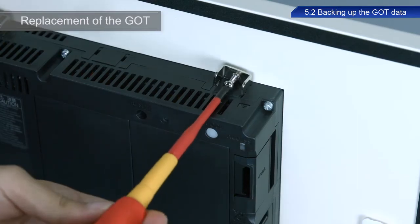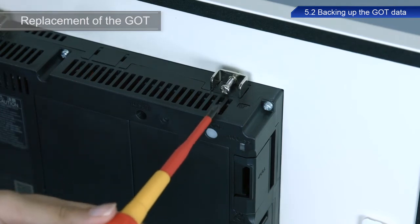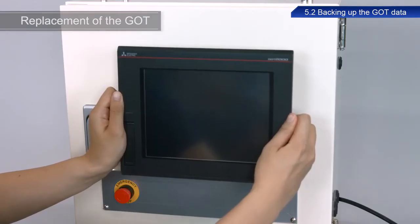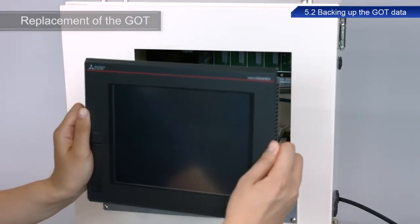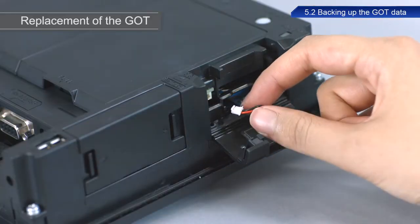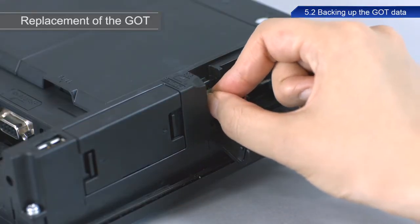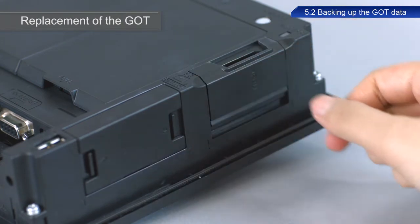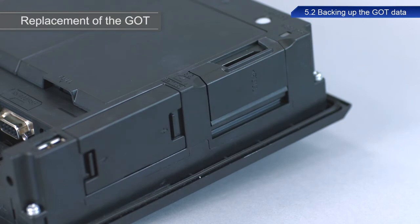The GOT is secured to the panel with mounting brackets. Remove the brackets to remove the GOT device. Next, we will prepare a new GOT. Connect the battery connector to the device. The battery is not connected at the factory to conserve the battery charge.